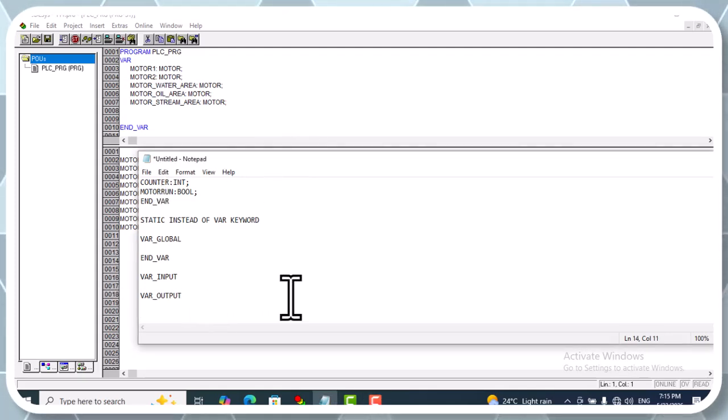And so, go to the next one, the VAR_IN_OUT, in and out. The VAR_IN_OUT is used when the function or function block needs both read and write access to the variable. Unlike VAR_INPUT, which passes a copy of the value, VAR_IN_OUT passes the actual variable address.